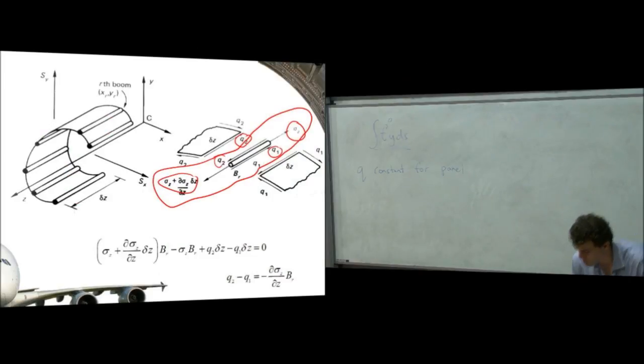If we do a sum of forces calculation for our boom here, the tensile force on the front end of the boom is the stress times the area.